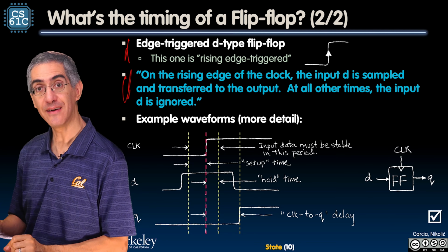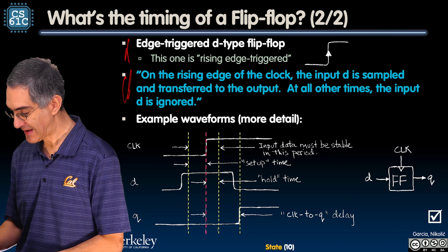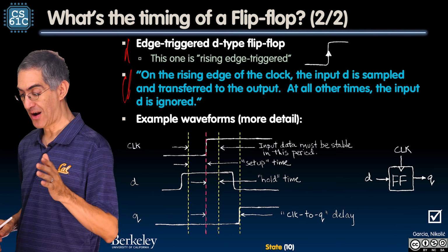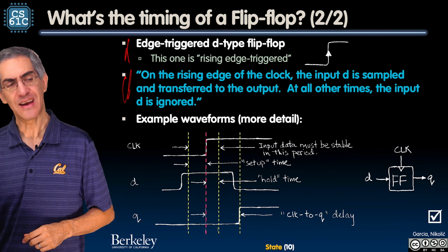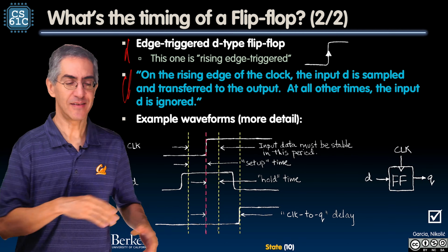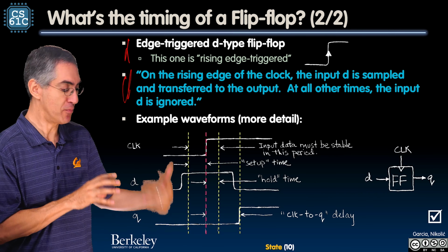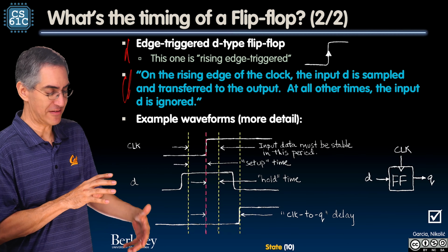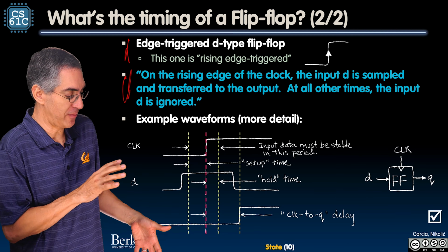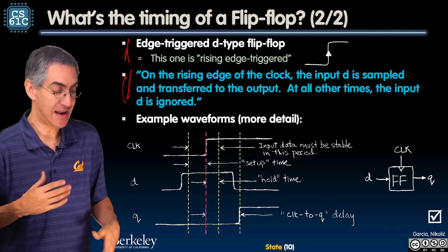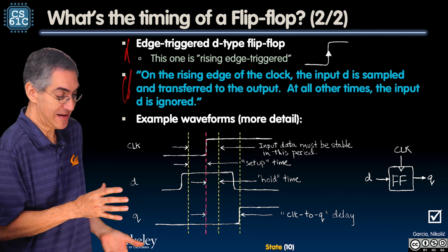So the red line is the rising edge of the clock. That's the important red line. And now here's the key. You're gonna say, well, Dan, while I'm turning around and grabbing it, can D just be moving around? Wouldn't you possibly grab a half if it's moving from 0 to 1? And the answer is yes. I could be in a really unstable state if, as I'm turning around to grab D, D is changing.